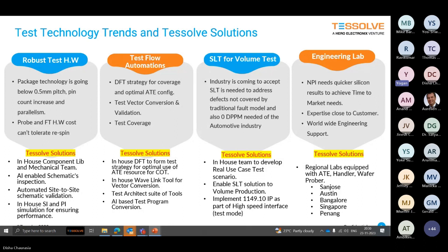And we have successfully evaluated some of the complex hardware, both ATE and system-level hardware, through an AI-enabled schematic inspection tool, which can take the BOM content of your schematic and check the components against the vendor's recommendation and find out if there are any deviations, from simple ones to even circuit-level ones. And if you design a multi-site schematic for a solution, we inspect the golden site for one site, and how this site matches with the other 8 sites or 32 sites you develop.